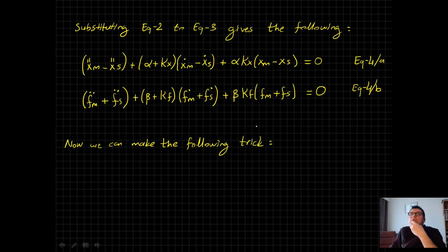I hope you remember the previous week's derivation. In grasping control algorithm and in the derivation that's made 1 week before that in the force control application, we discussed that the environmental impedance consists of three main items. One is mass times the deflection's second derivative. The other is the damping ratio times the deflection's first derivative. And the third one is spring constant times the deflection itself.